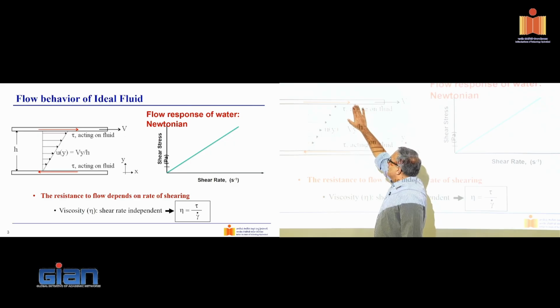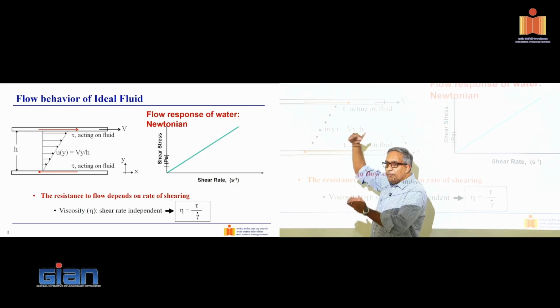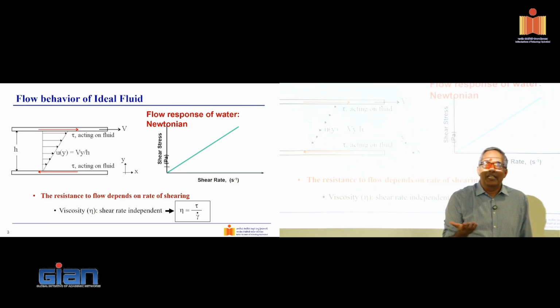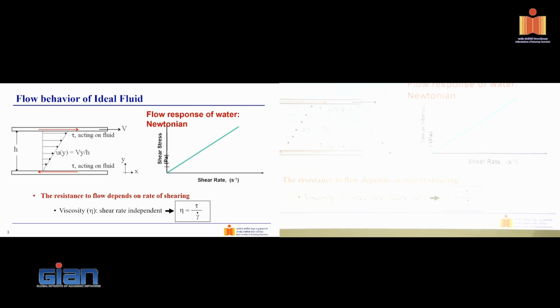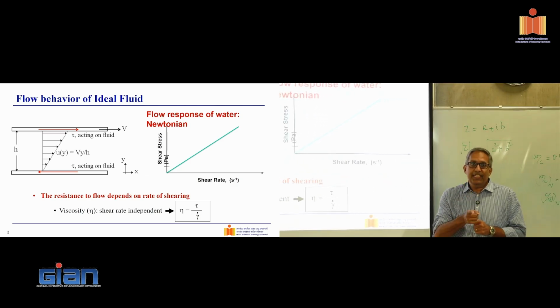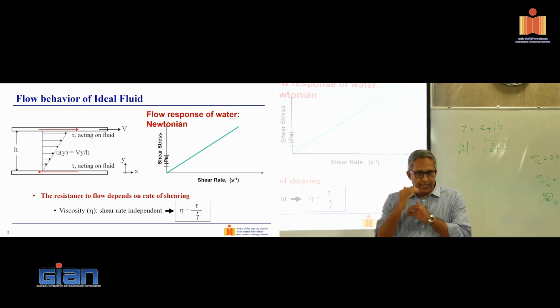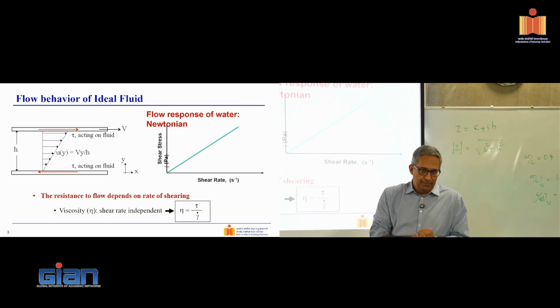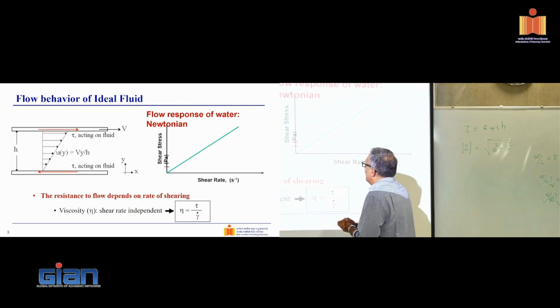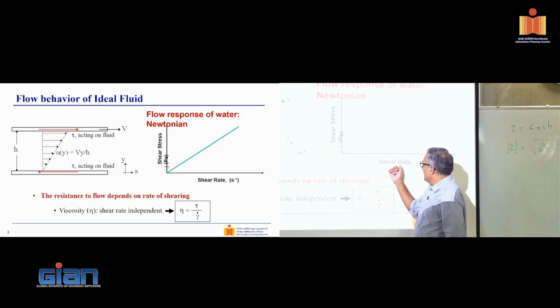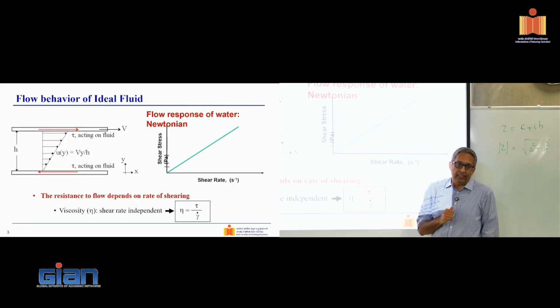If you look at it, the liquid is getting sheared between these two surfaces, and we are trying to measure what is the resistance that the liquid is giving when I'm shearing it. Shearing it under a dynamic condition, right? So shear rate, okay? How do we measure that? Well, we measure the shear stress as a function of shear rate.